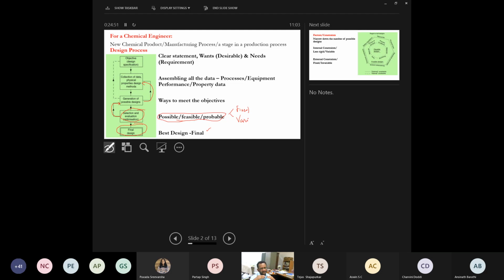So the feed quality we will not get continuously in the same range. It has some range. The quality of the feed varies continuously, and it will reflect on the performance of the equipment. So we should provide some contingency, or we have to over design by applying a factor of safety. Those things we have to do.